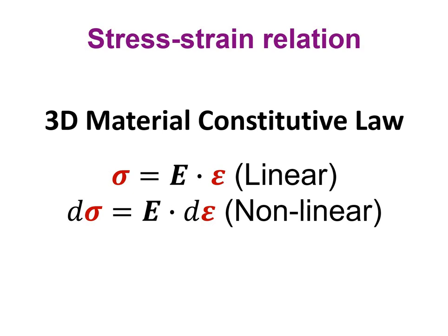And when you have a nonlinear relationship between stresses and strain, the stress tensor has to be represented by the differential of the stress tensor, equal to the stiffness matrix, or a stiffness tensor, that will be variable in this case, because the relationship is nonlinear. It will depend on the degrees of strain, and the strain will be represented by a tensor again, which is actually the differential of that tensor, because the relationship is nonlinear.